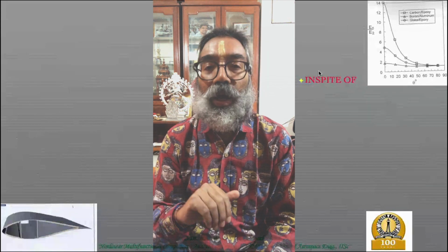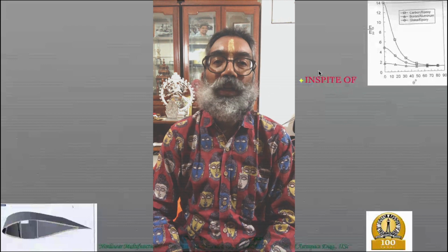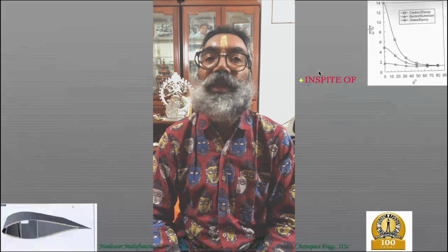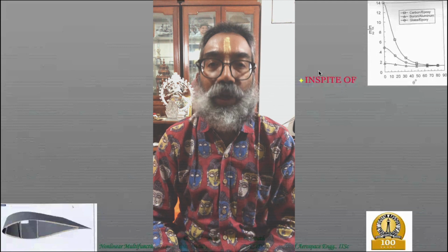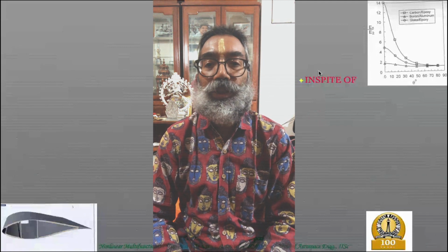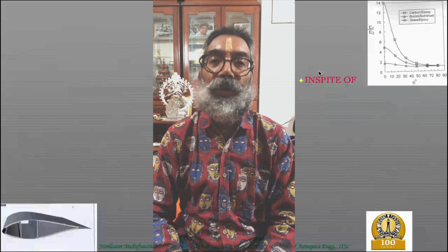particular direction. And usually when you're designing a structure, you know what are the dominant loads, and therefore not only the magnitudes of those loads but the directions of those loads as well. So since you know a priori the direction of the dominant load, you would tend to design your structure such that you put all or most of your fibers along that particular direction.